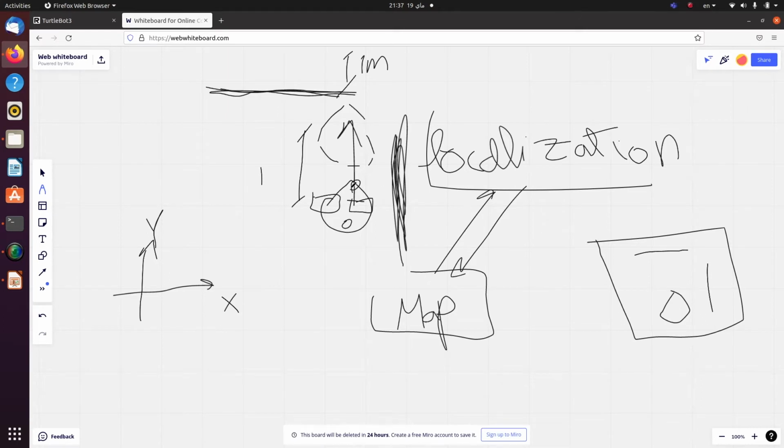So later you will have some prediction of where you are now. So you'll say that according to my dead reckoning sensors, I moved like 1 meter. And this 1 meter is quite noisy, but it's the best estimate I have so far. And then I had another shot here, which indicates that this wall is now at a distance of like 0.9 meters, which means that I most likely moved a distance which lies between 0.9 and 1.